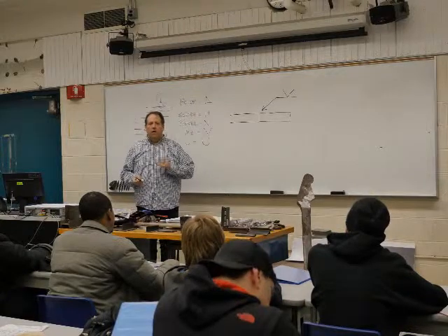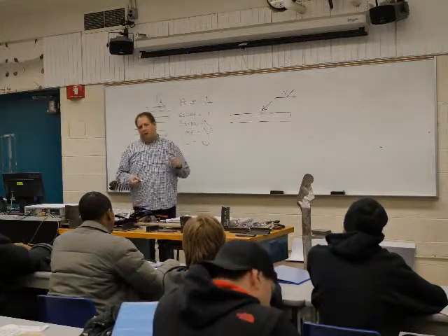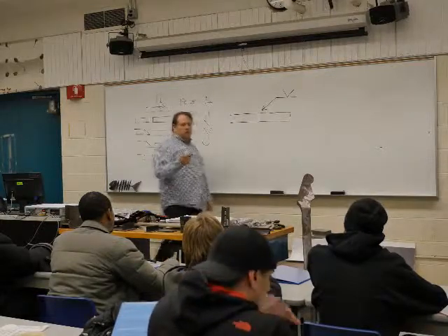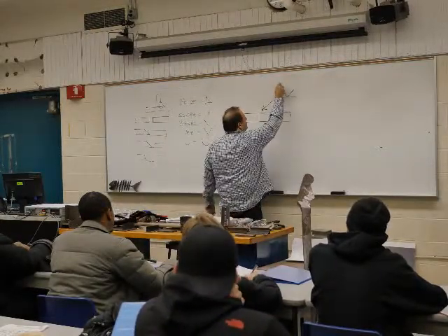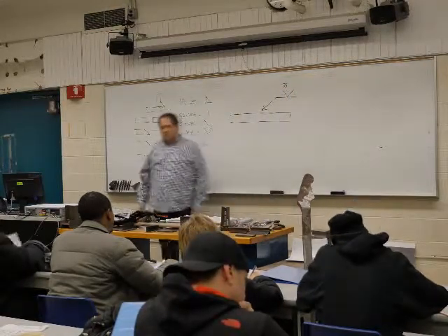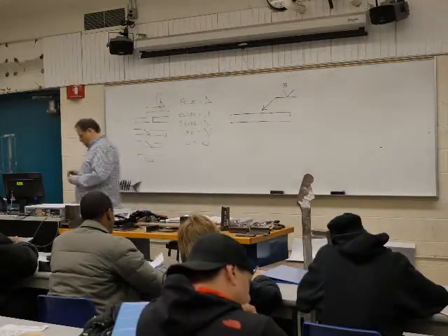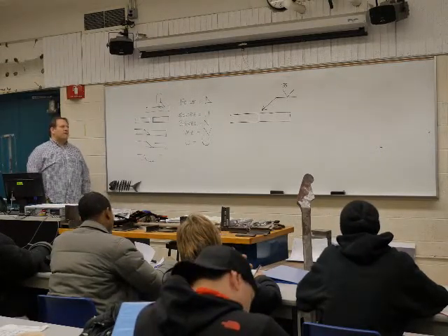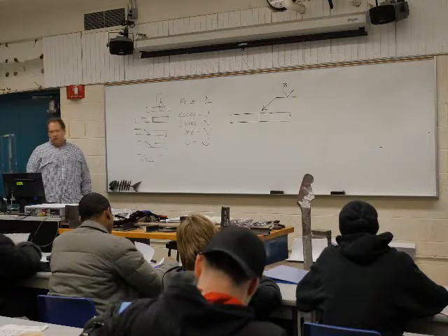They don't go from left to right here, we start stacking. So it's a V groove. Now we need a dimension. And the dimension usually goes about right here, and this is going to be in degrees. So that V groove has to be 75 degrees.